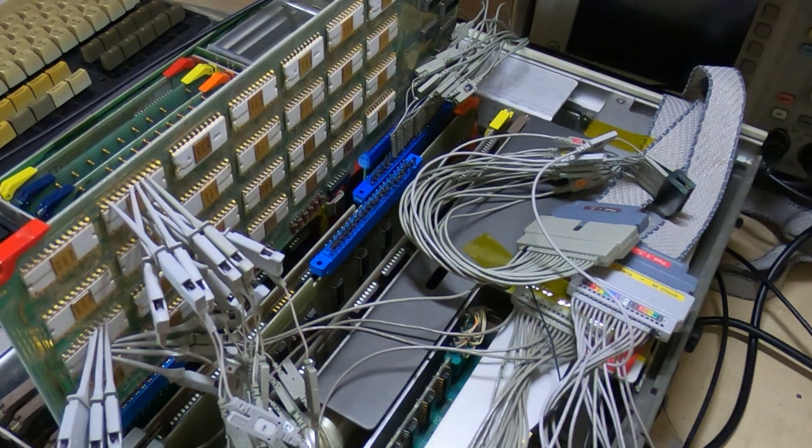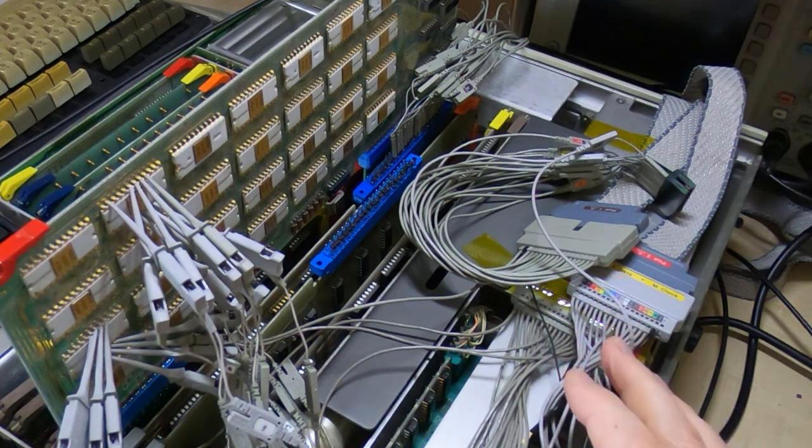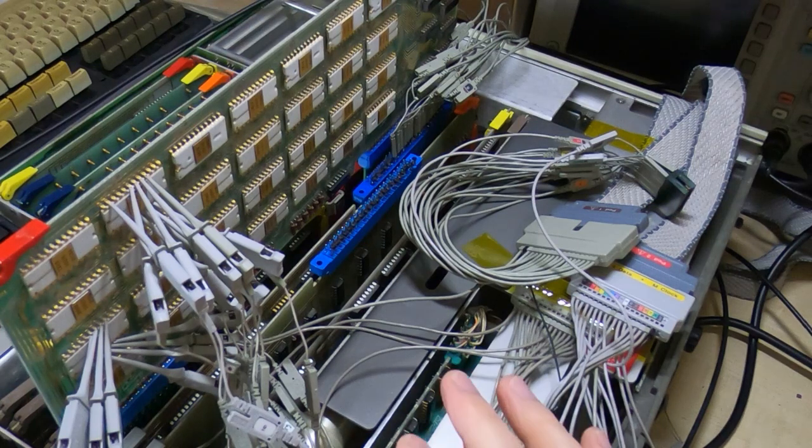I've never seen a piece of equipment with so many failed ICs, and that started giving me some concern, based on the nature of the circuits in this machine, that there was something more serious going on. Usually this sort of thing is power supply related, but I'd eliminated problems with the supply. I've very thoroughly investigated that. The reset circuits seem to be working, the power supplies are stable, they come up in the right way.